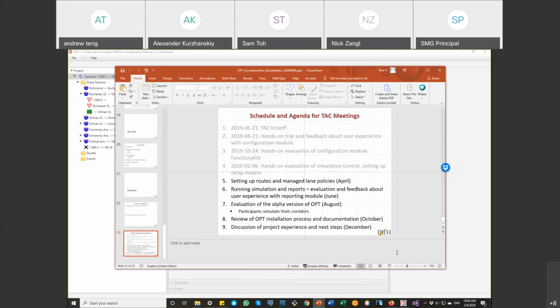In the past, and this is just for everybody who may be interested, before OPT existed, during the CSMP age, we took the SCAG model data and put it on the freeway that we were doing the CSMP for, and we'd have to reduce the demand significantly because this is a demand model, not a traffic model. So there is no way to push all the demand that the SCAG model tells you is going to go through at certain locations. And then when we calibrate it correctly, then we can do operational analysis. So it's very challenging.